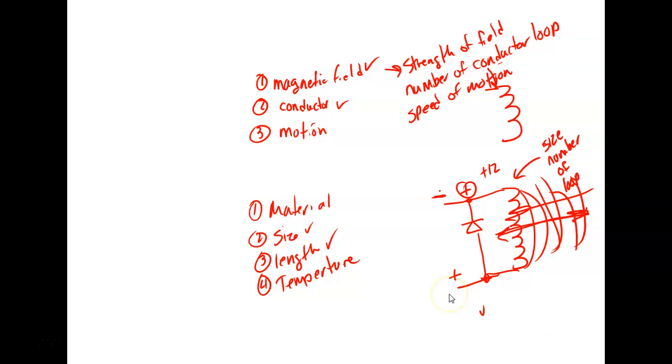So we had a big printer that we were working on that had a bunch of solenoids in it, and one of the transistors that fired the solenoid went out. We replaced the transistor because it was bad, but guess what? We didn't check the diode. And we fired this thing back up. I don't remember how much that big printer cost.